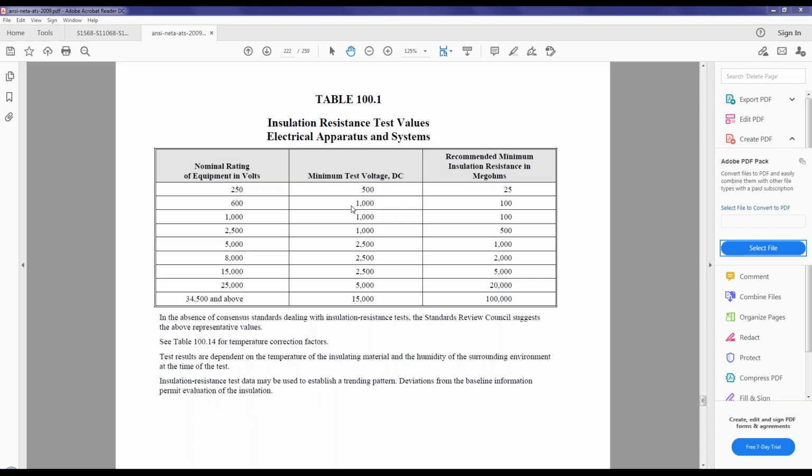So in my understanding, they want to test cable using our 15 kV insulation resistance tester. Theoretically, it will be the same method. We produce the DC output to the cable, but the expected result will be different, because our insulation resistance test will provide you a megaohm value, and when you use the hipot test, the expected result is in milliamps or microamps.